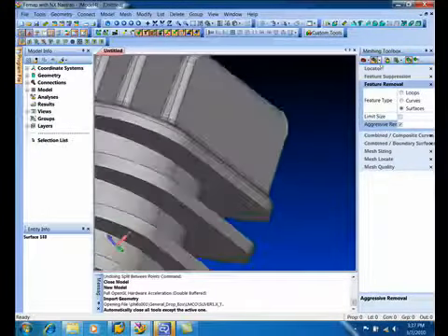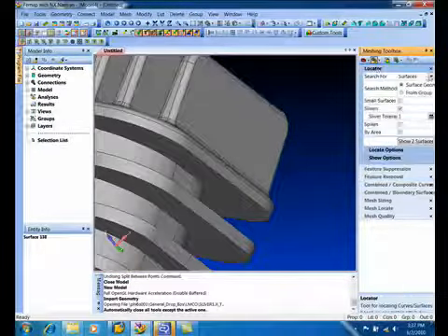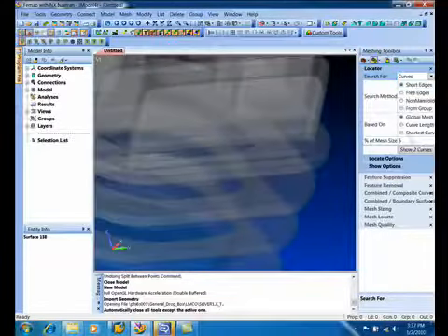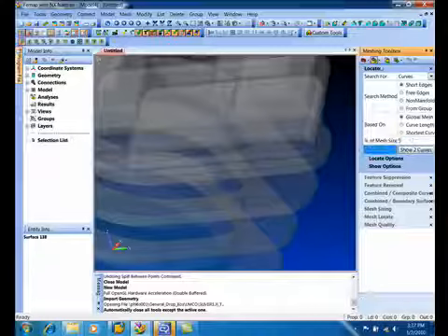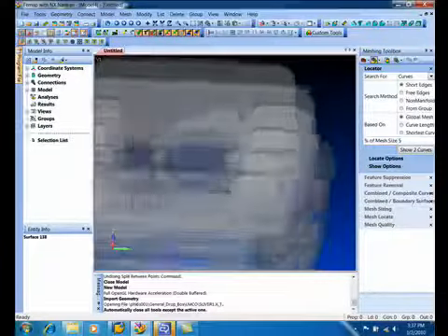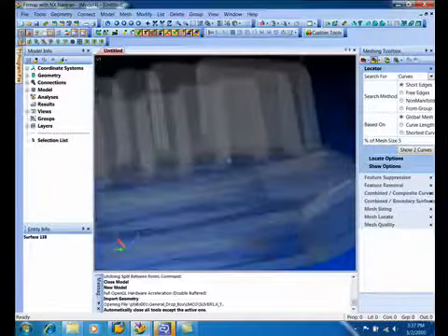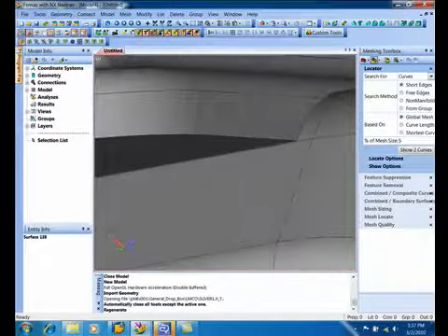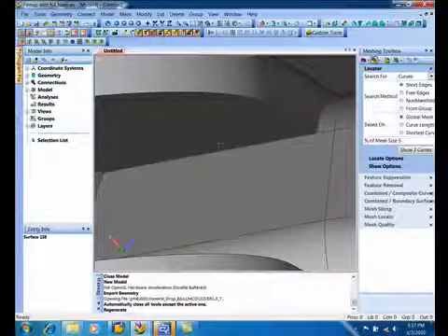Let's make sure we don't have any short edges in the model. So go back to the locator, go to curves, and let's see what we've got here. There are 2 curves that are pretty short, and let's see where these are. It zooms in. Oh, looks like we have another little ledge in here, this little flag-shaped surface.